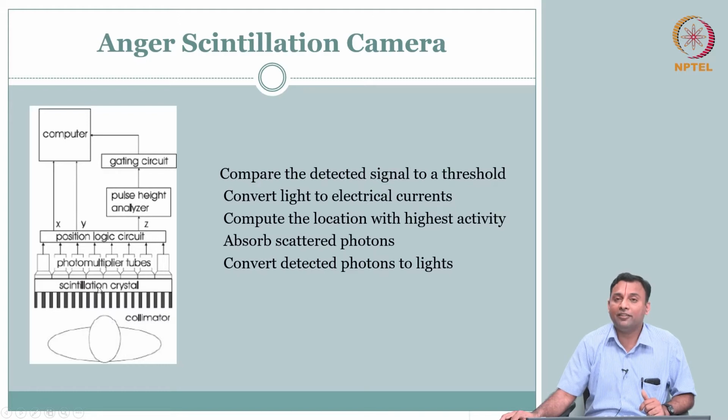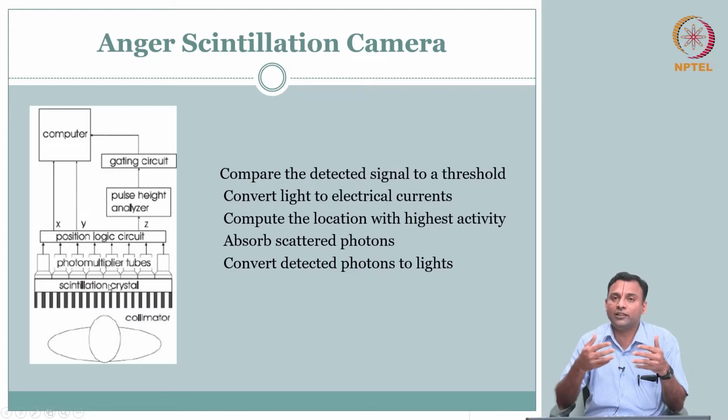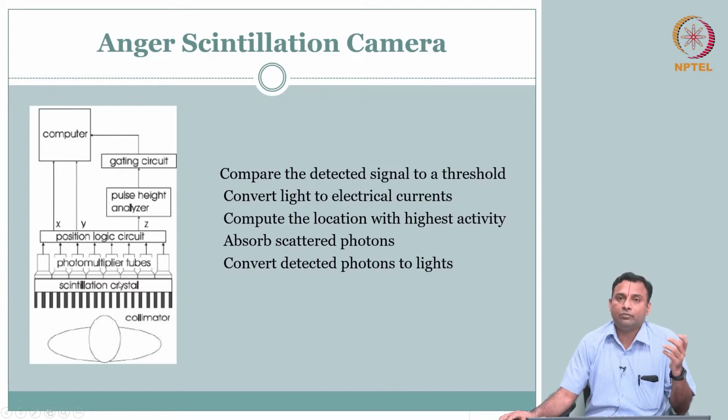So, maybe that is giving, so photon is interacting with the crystal, right, that thick. So, you could get Compton scattering there and you could get less energy that is coming out, Compton scattered. So, now the question is, do you want to interpret that as a signal or is it Compton scattered? So, we can be energy sensitive. If we are energy sensitive, we can say, oh, because I know what is the gamma the radio tracer is sending out. If it is within certain tolerance, I know it is the real signal coming from that source. If it is less than that, I know it is scattered photon. So, you have some thresholding criteria, we will look at it.